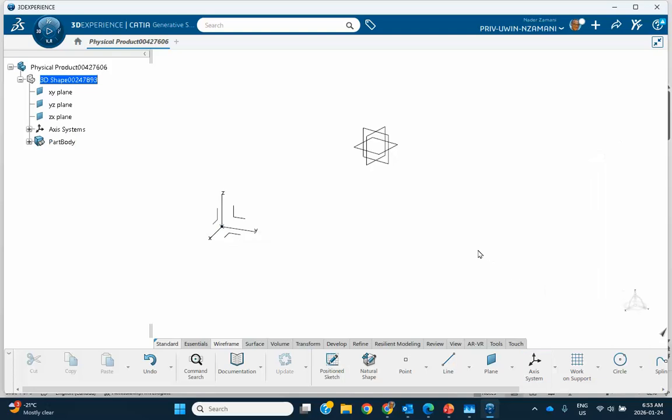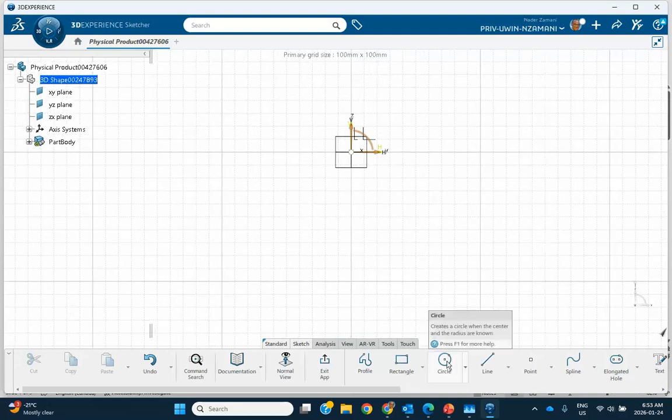So the sections that I'm going to draw, one of them is on the vertical plane here, and the other one is on the vertical plane of this axis system. So they're tilted with respect to each other. I could have done it with two being parallel without creating this axis system. But on that vertical plane, I will sketch. Let me sketch two things. One is a circle.